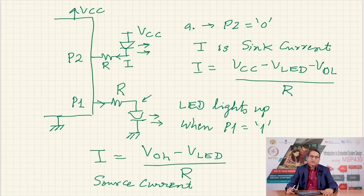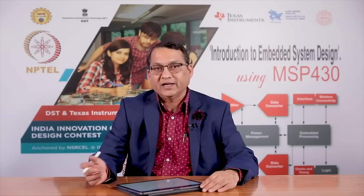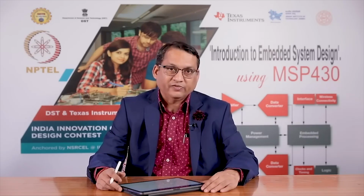The intensity of light that is coming out of the LED is proportional to the current flowing through the LED. And so, if the current you need for the intensity is less than 30 or 40 milliamperes, you would be able to connect it directly to the microcontroller. In case you want higher intensity, and you need much more than 40 milliamperes of current, we will have to resort to some other circuit configuration.